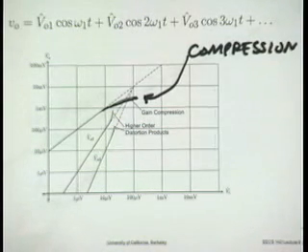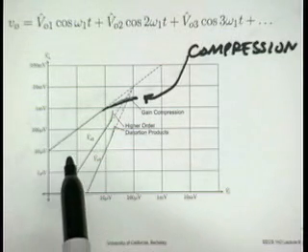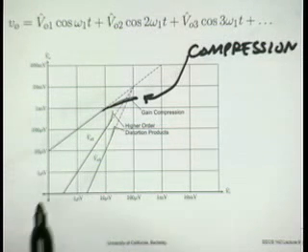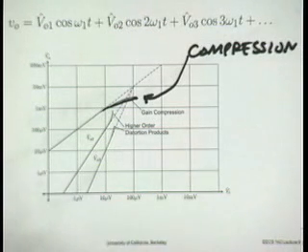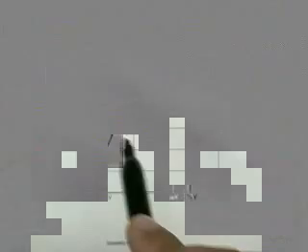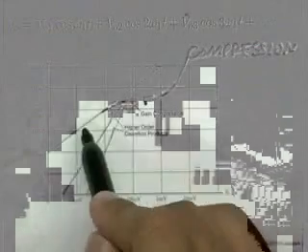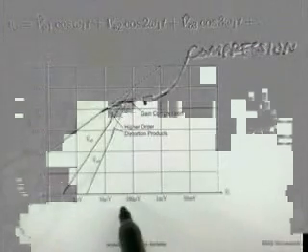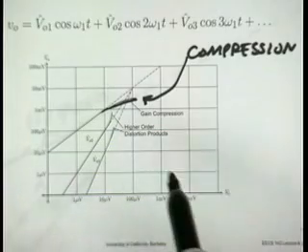Subtractive effect of the third harmonic. Very good. Remember, we found that for very small signals, the fundamental is essentially generated by the linear term, A1. But remember, we looked at the cubic term, A3, and we found that A3 also produces fundamental. In fact, what we showed was any odd power will produce fundamental. And depending on the sign of A3, A5, A7, and so on and so forth, that might be subtractive. And so here, I'm assuming that it is subtractive, and so it's compressing the gain. So the gain's going down for large signal input. Okay? Same thing happens here.